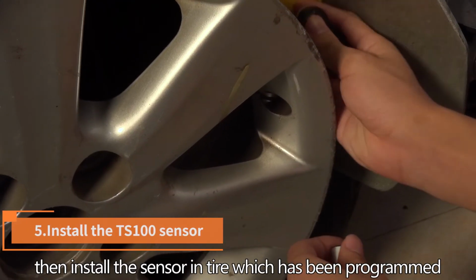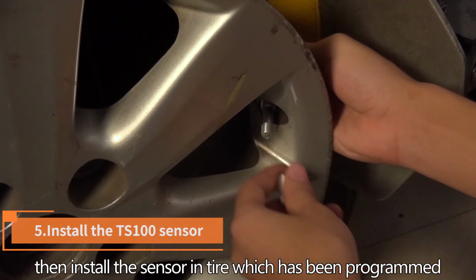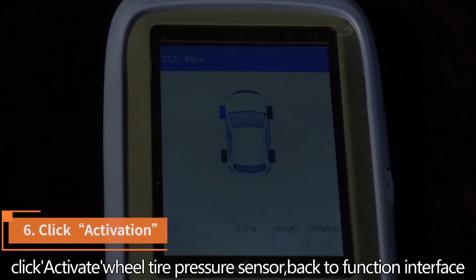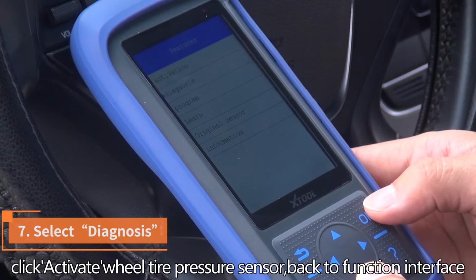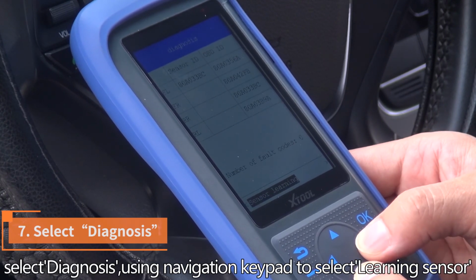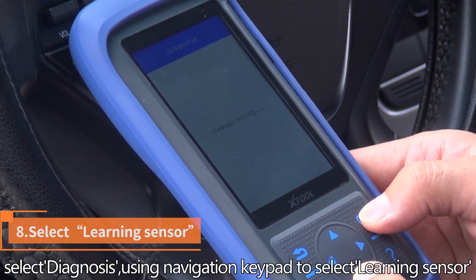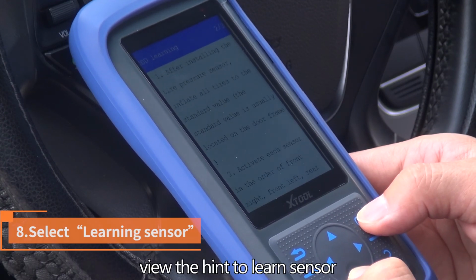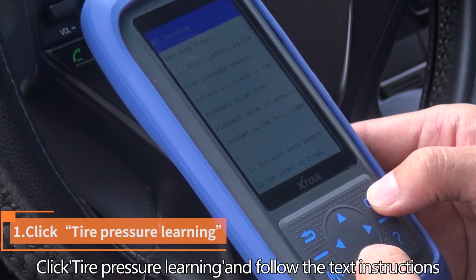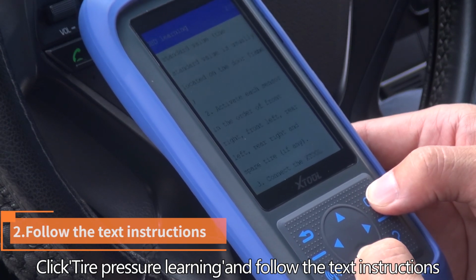Then install the sensor in the tire which has been programmed. Click Activate Wheel Tire Pressure Sensor, back to the Function Interface. Select Diagnosis. Using the navigation keypad, select Learning Sensor. View the hint to learn the sensor. Click Tire Pressure Learning and follow the text instructions.